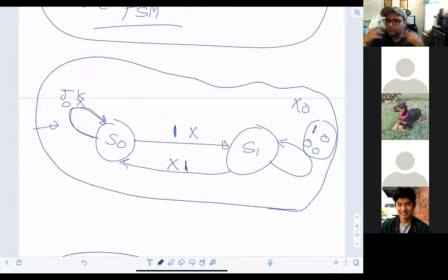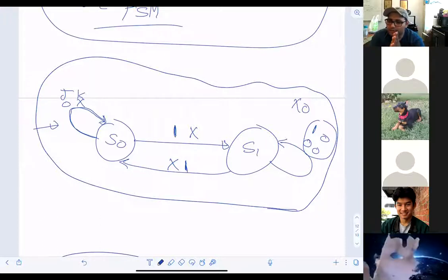This table is basically the one we start with. We move to the characteristic. From the characteristic, we move to the excitation. Then we move from one flip-flop to the other using scientific steps: defining what is available, what is required, and defining the characteristic table of the required. From there, we can apply the excitation of the available. After that, we do the Boolean algebra or Boolean equations coming from the K-map as optimization techniques we learned. And then we make the implementation using the flip-flop surrounded by some gates to make a connection between the available and the required.